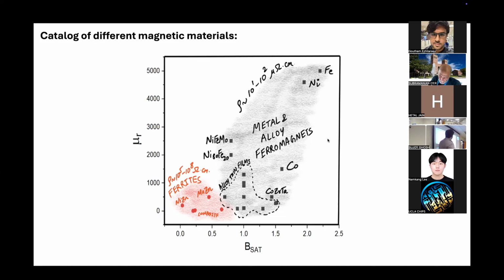If you go for a ferromagnetic, you can get better behavior in terms of permeability and saturation field as well as frequency, but then you will have to laminate the material. And sometimes doing laminations on chip is very difficult. But if you use ferrites, you don't have to laminate, but then it doesn't go to very high frequencies. It also has a lower saturation field and a lower permeability.